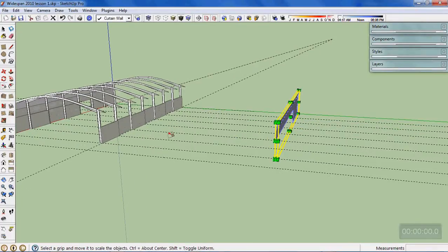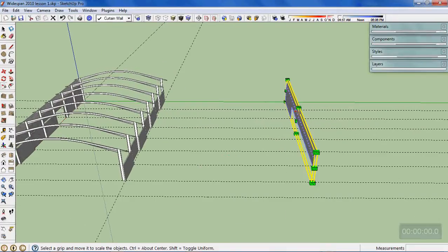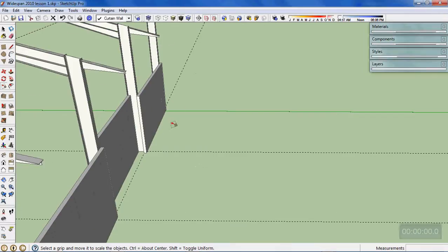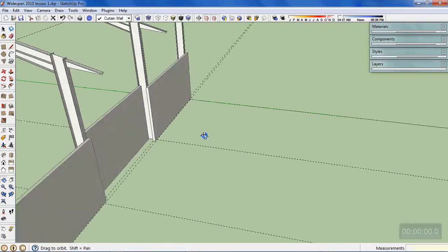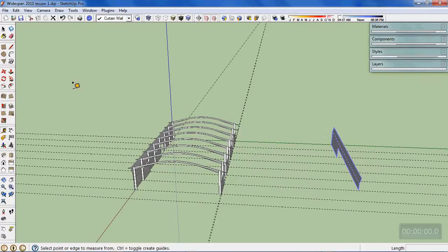Now I want to locate that back in the plane, which from memory was 178mm away from the column set out line. So I'll grab my tape measure and from my column set out line come back 178, and that's the line that I now want to move all of this back to. So if I go and grab the move tool now, it's still highlighted. I can go and pick it up